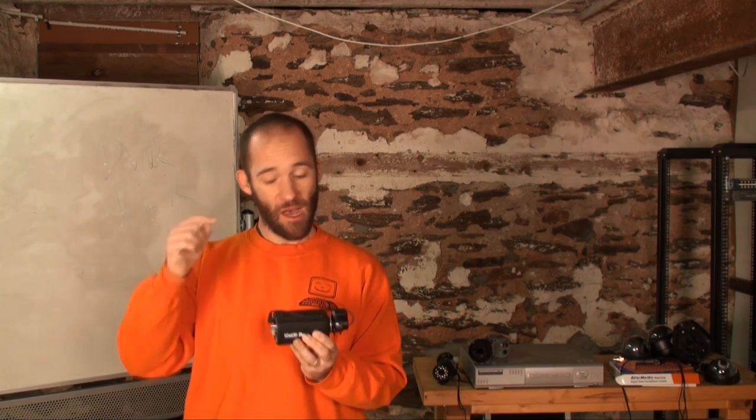You can also go all the way down to 320 TVL. These are very low quality cameras. That's what you have to look at when you're buying your camera. 320 TVL is about the lowest quality analog camera that you can buy. Essentially, you see that a room exists and you see a blob moving across the room. You might be able to see the blob had an orange coat on. You might think the coat is brown. But that's the issue. So TVL is resolution. We're dealing with these analog cameras. Like I say, 320 is about the lowest you can go.